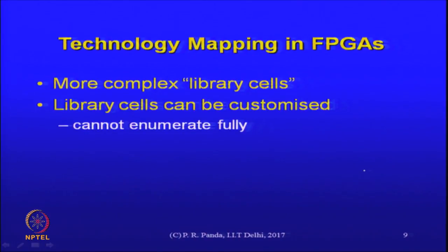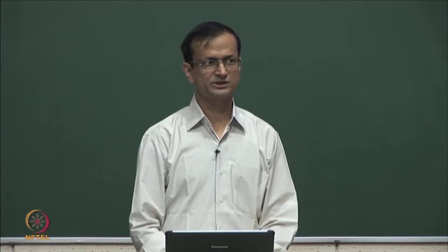D flip flops are fine. Yeah, they are there just like they were there as cells in the standard cell library, and in fact we have embedded some D flip flops in each of these CLBs. So that is fine. So, just the logic itself, the logic there was implemented in terms of standard cell library elements.